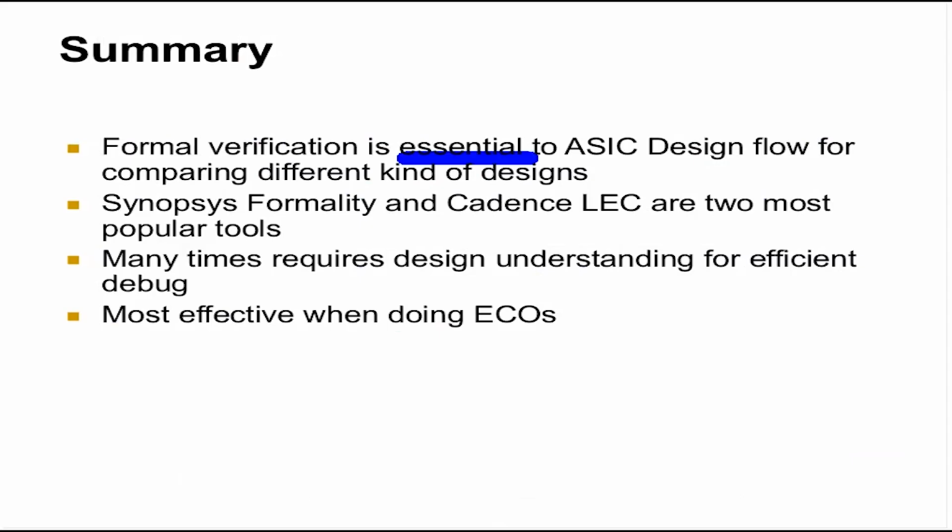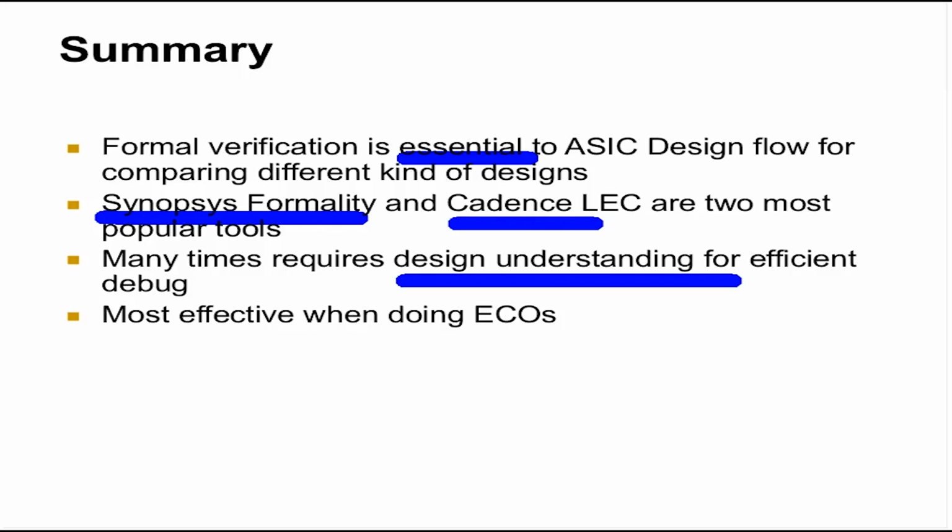Every chip design team in the industry uses formality, and there are many unique uses of formality, right? These two tools are the industry leading tools for formal verification. Many times it requires design understanding for efficient debug. This is the problem. As an ST engineer or as a synthesis engineer, usually synthesis engineers are most comfortable with formality because the setup is the same, right? But many times you will have to go back to the designer and get him to fix his RTL or help you understand the formality non-equivalences, right? So the tool is essential.